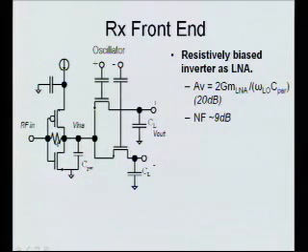So the gain here, it's worth noting, I made the resistor big. I spent all this time matching the transmitter, but the receiver is not that well matched. I just try to make this node look as high impedance as possible and get as much swing as possible. The matching's not great, but there's no transmission lines or anything. It's just an antenna, so that actually doesn't work too badly.